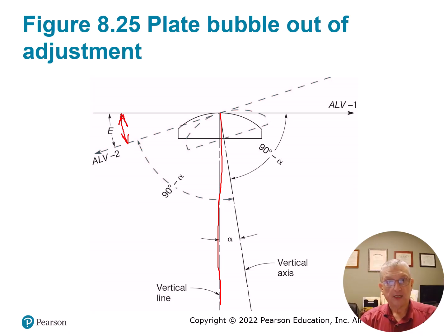And so if you're out 15 minutes here, we're not talking about looking at an angle out there, we're talking about how much out of level the level head is, or the tribrach is. 20 minutes is nothing in a few inches across the base of an instrument. You can't see it with the naked eye. You have to try really hard to find it with an instrument.